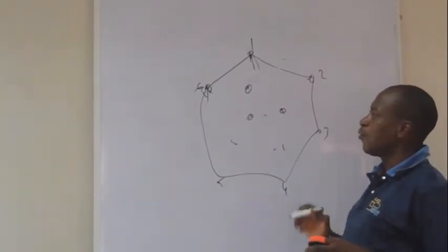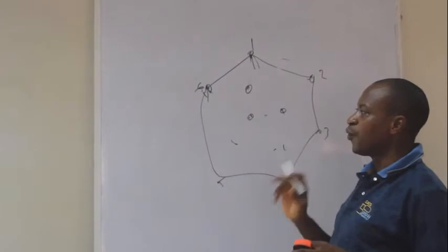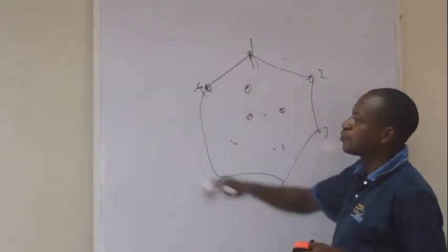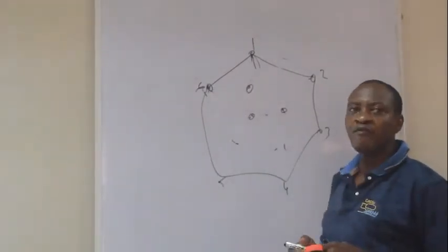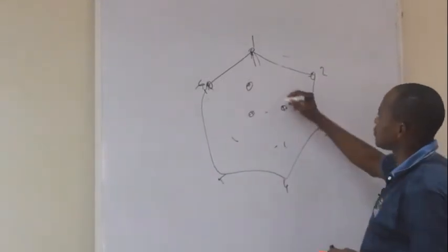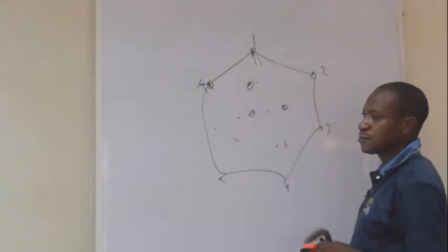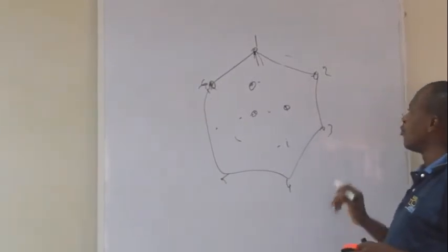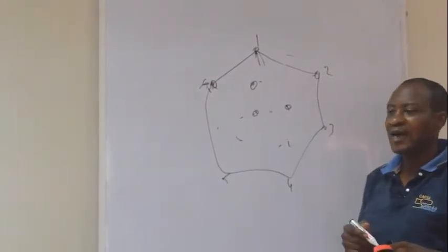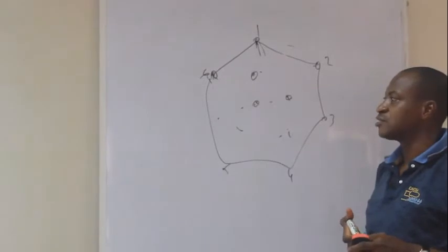And that is why it is advocated that we carry out our survey based on the principle of the whole to the parts. So if there's any error, we can be able to locate it and curtail it.